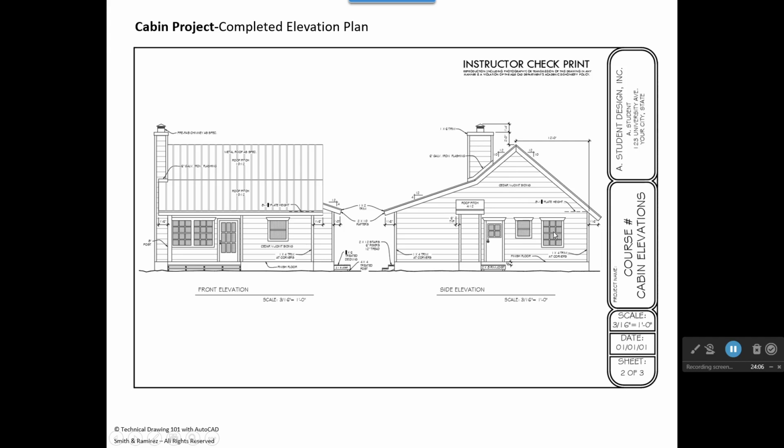All right, so as I was saying, you'll start by drawing this wall actually over here, and then we'll build this first pitch of this roof, which is called a 10-12 slope. And then we'll mirror that. We'll mirror this roof around, and then it will intersect with another slope that's a 4-12 slope. And remember, this is 32 feet from this edge here to this edge over here, and we see our porch steps in the side view.